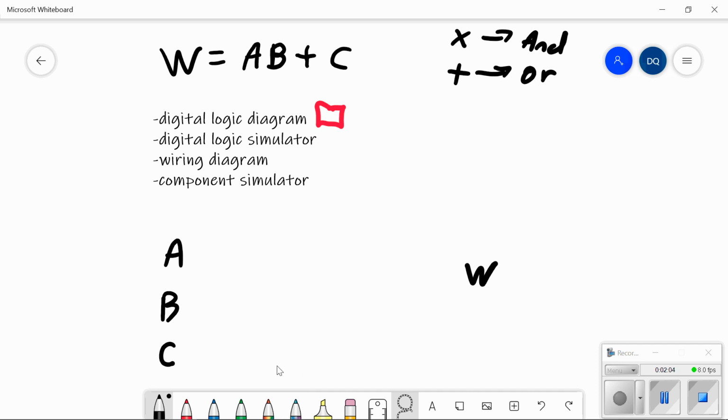We're going to have A and B, so I'm just going to draw an AND gate that connects A and B. That makes the result on this wire here A and B. Now you don't have to write those in, but when you start, you probably should, just to learn what it is you have. I now want A and B or C.